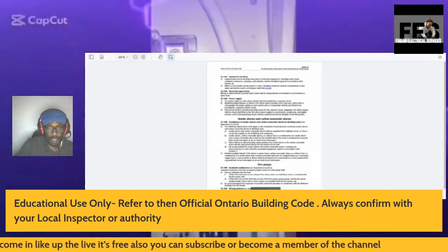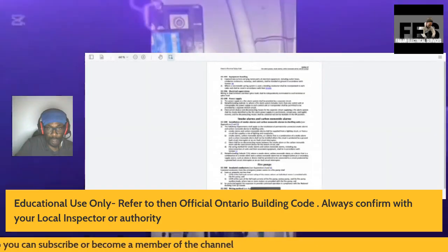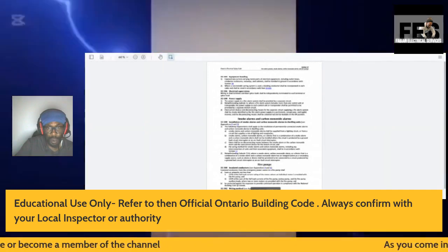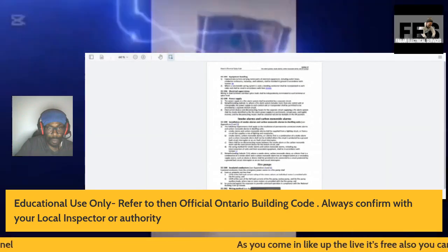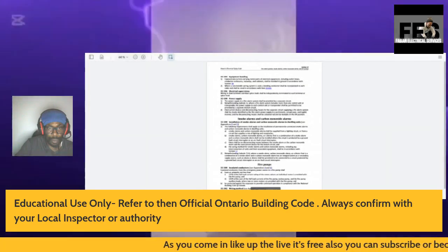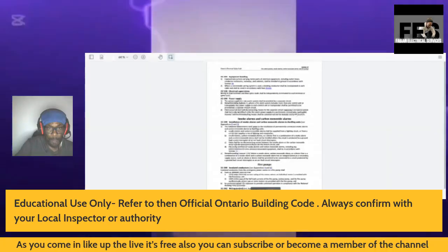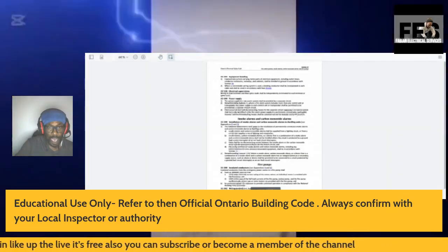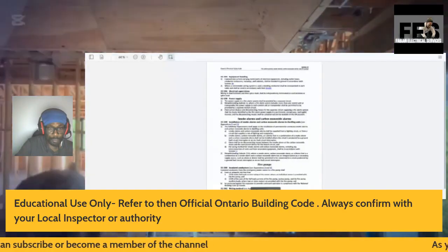Notwithstanding sub-rule 1, where a fire alarm system includes more than one control unit, the power supply to each control unit shall be a separate branch circuit. That means a separate branch circuit just means you need an individual circuit to provide power.